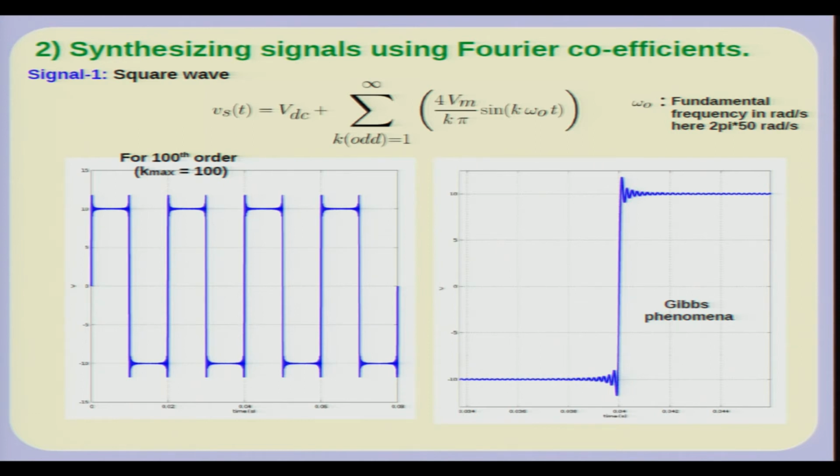So, if you take a square wave, this is what you get. Because the jump from 0 to 1 occurs at t equal to 0, you have only sinusoidal components and no cosinusoidal components, but in general you could have both. And the other thing is, because it is a symmetrical square wave, that is, the top half and the bottom half look alike, there is half wave symmetry, and you will find that there are only odd harmonics in this.